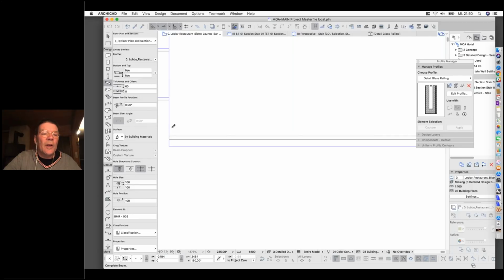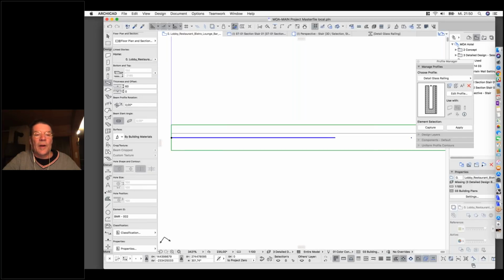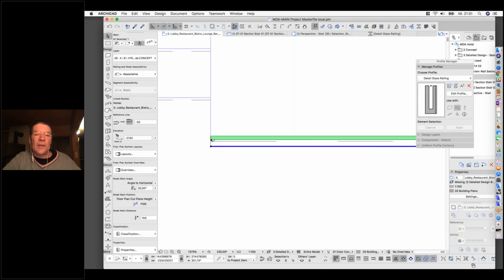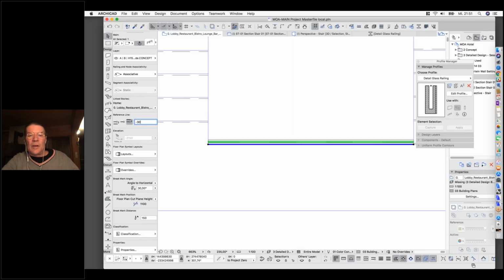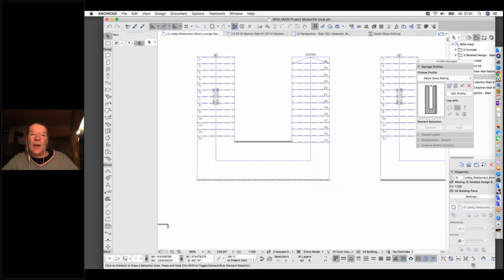When you draw it, you can see where the steel panel is. It's on the front. So I just drag it here. And the only thing is I have to know where I have to place my rail, which is sometimes tricky to find afterwards. And I have to define the distance of the rail. It's far outside, and as I remember, it should be 30. Yep, that's right. So the detail is almost ready. And once you have done this setup, you can head on.